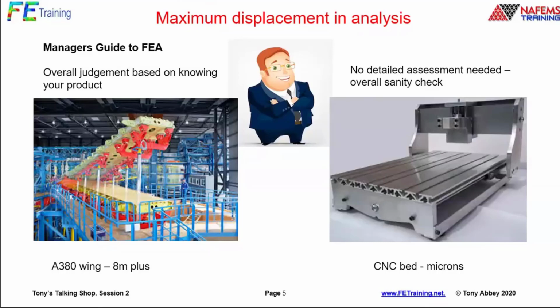So I recommend that somebody calling in saying they don't know very much about FEA: hey, you know your product. You know your product. So that's our first check. First sanity check: is the number about the right order? Again, no calculations, no knowledge of engineering FEA needed. So that's my starting point, and that's a great way of starting to filter down the result.